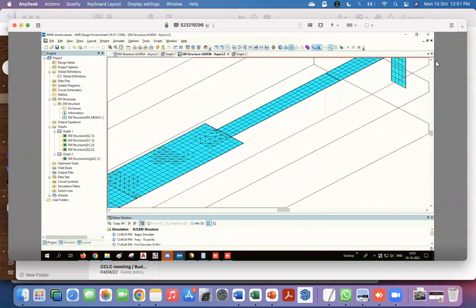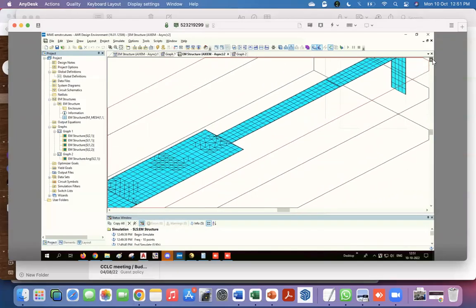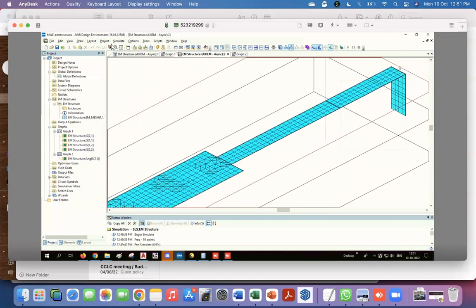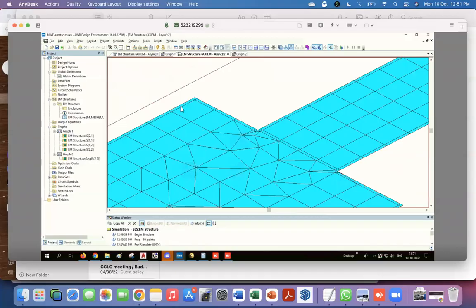Some of these things, I think you can control; you can force it to do it a specific way. But I guess we noticed this last time also. We can also look carefully at the edges. It does some finer boundaries, because again, the edge of a metal is where there's a discontinuity, right? There's a different air or dielectric on the other side. So it makes sense that it tries to solve it in a more refined way.